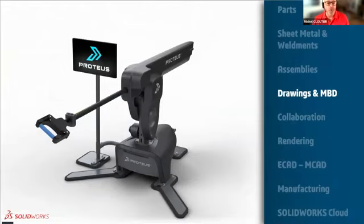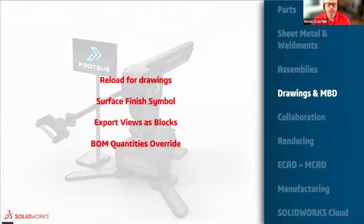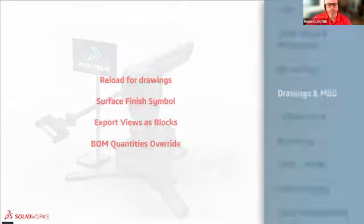Now let's move to drawings and model-based definition. So we have quite a few enhancements again in drawings, as in all areas of the software. We have the ability to reload for drawings. We have a new surface finish symbol, or actually improved support for the standards for surface finish. We have the ability to export views as block that can be really useful if you're exporting to DWG, for example. And the ability to override BOM quantities.